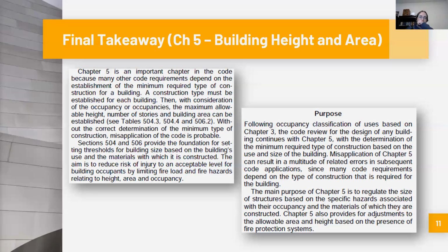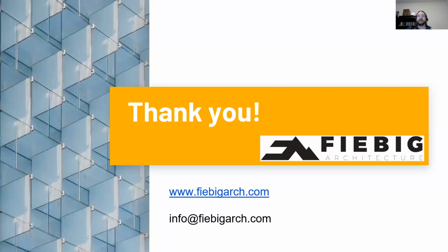So that being said, that's the end of today's lesson. Once again, just trying to emphasize the importance of understanding combustible materials and non-combustible materials. If you're an architect or a building designer, you want to make sure that whatever materials you use or specify in the building comply with the construction type assigned to that building, in order to make sure that the building is appropriate in its size, height, number of stories, area, based on those materials.